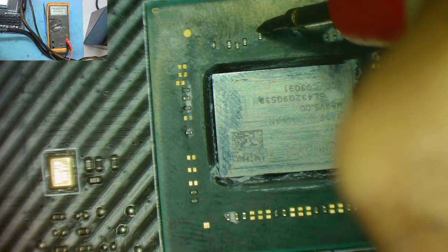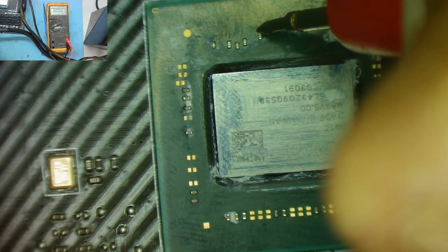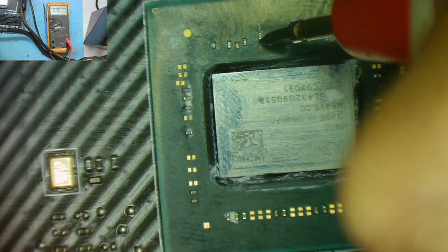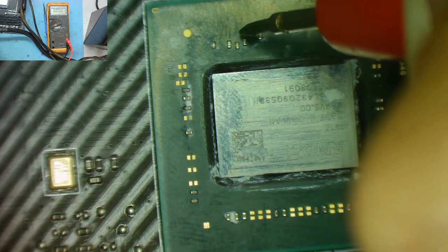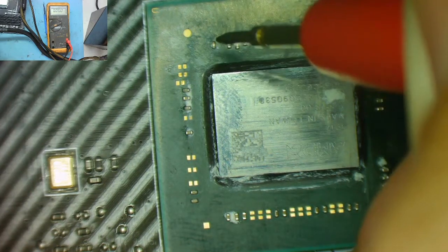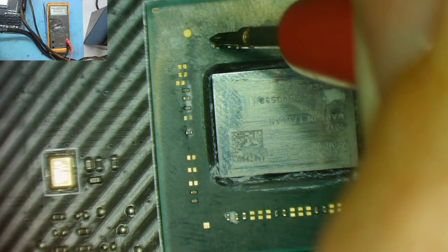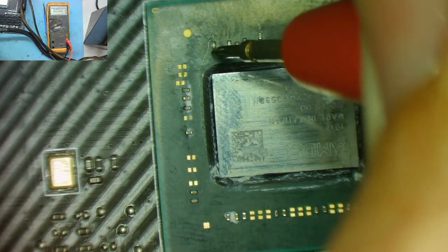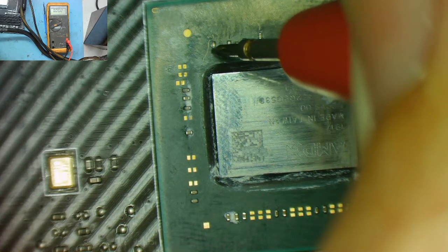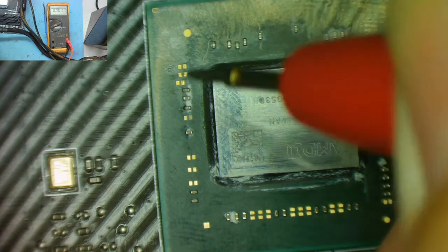Bear in mind this north bridge and that Super I/O will have more than one power supply. So you won't expect there to be power on all of the capacitors, just the ones that happen to be on the voltage rail. That there's a standby, nothing there. We don't know which end of them is ground, so we have to check both ends. Nothing there.